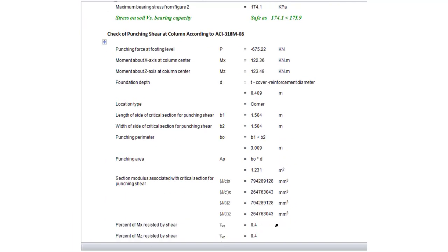This is a detailed punch check calculation. It includes the calculation of the moment transferred from the columns to the mat foundation by eccentricity of the shear. ASMTower automatically detects whether the column will be considered a corner, edge or intermediate column in the punching calculations.